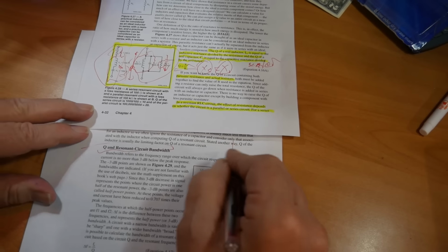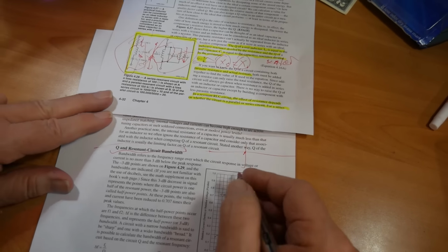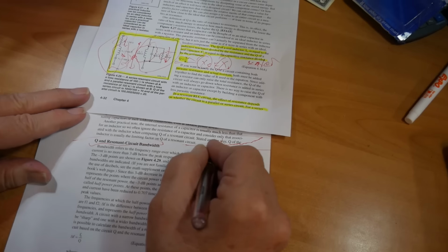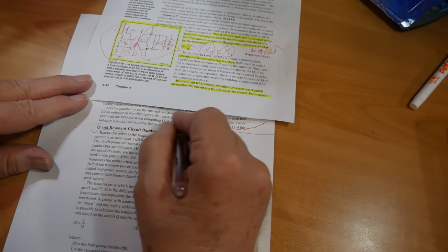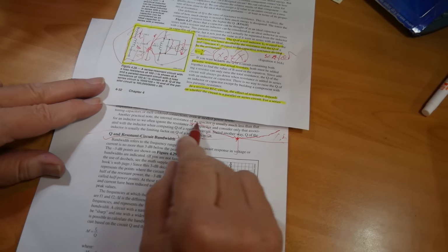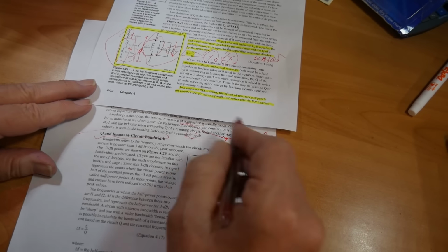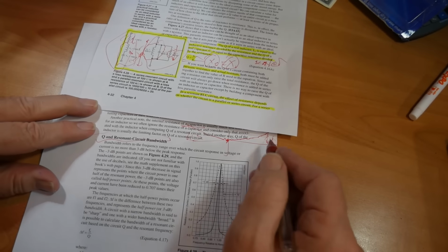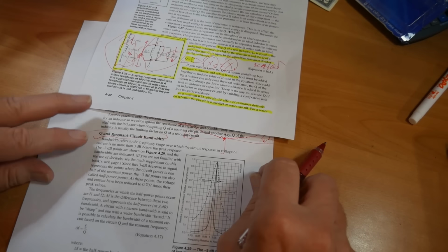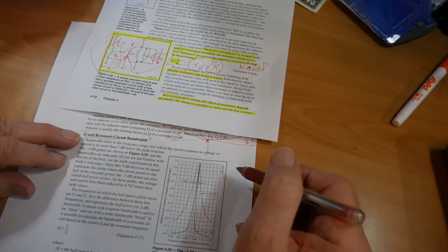If you have a dipole antenna, it's a resonant circuit, right? But it resonates only at one frequency. And then you start getting your SWR coming up a little bit more on either side of it. And you want to keep this at about 1.5 on either side. If you have a lower Q antenna, you will lower this and it will be good on a wider frequency band. Dipoles are pretty good. They'll cover the whole band except on 80, okay? Where dipoles have too high a Q to cover all of 80 meters.